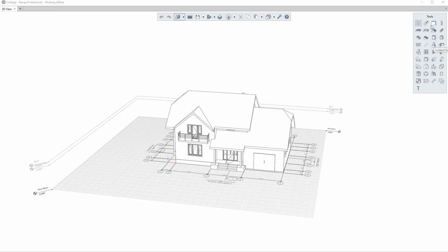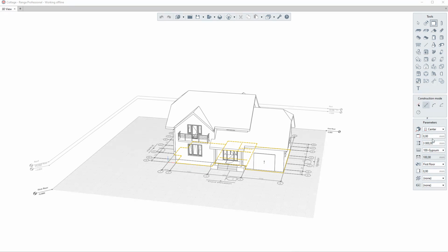With the help of the Tools panel, we place render objects in 3D view. Let's select the Wall tool to see how it works. We will build a fence around our cottage. The wall has a set of individual parameters as well as other render objects. We may see them on the right after activating the tool. In this lesson we will not go into detail about these parameters. We will only change the wall height to 2000 mm and the material to wood.